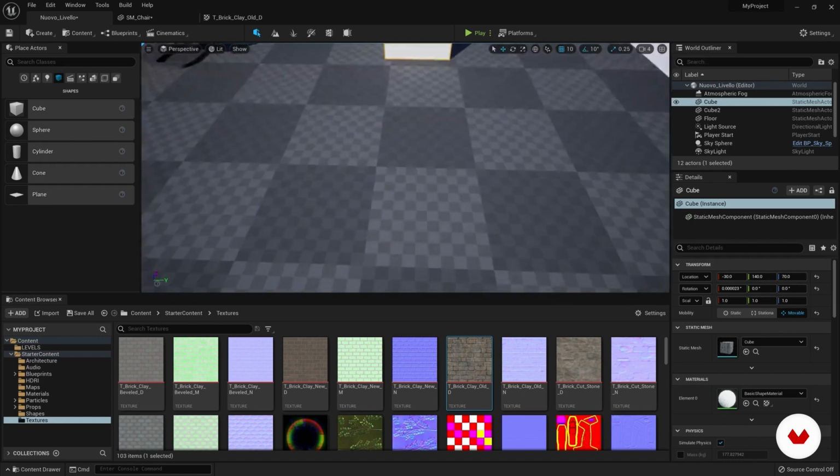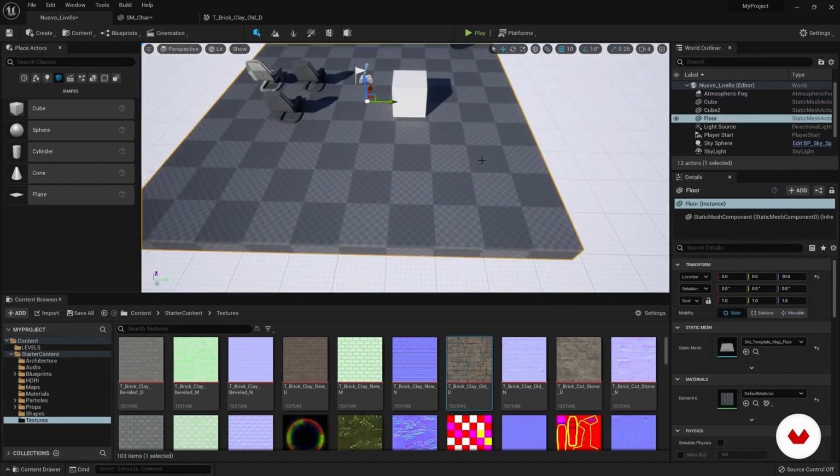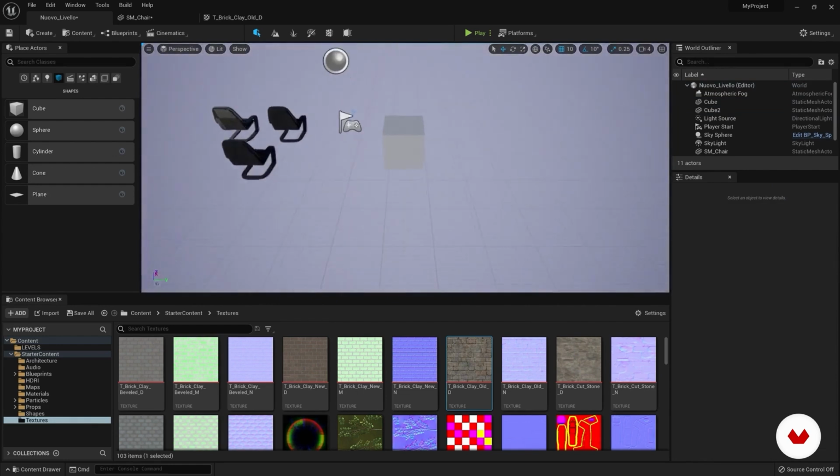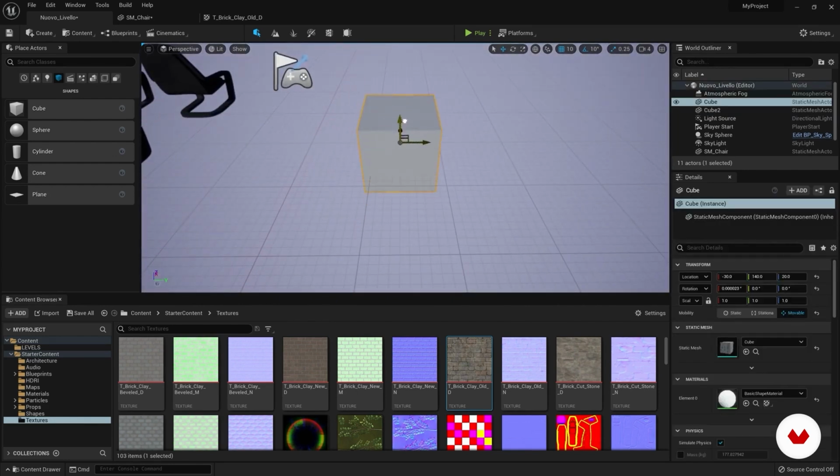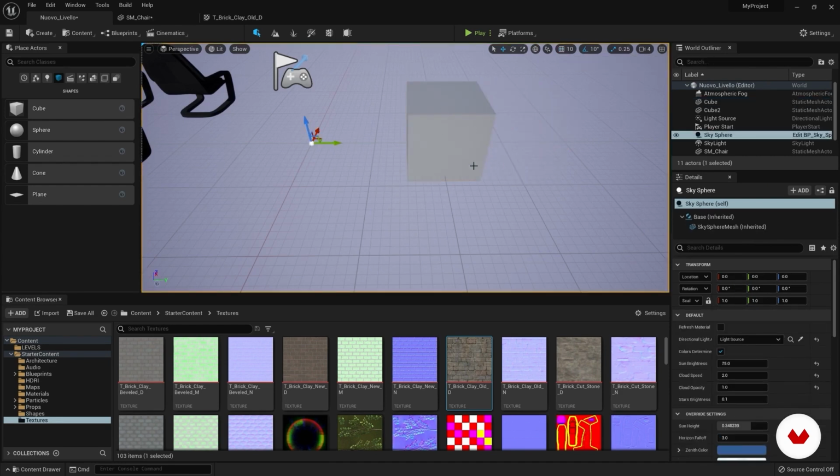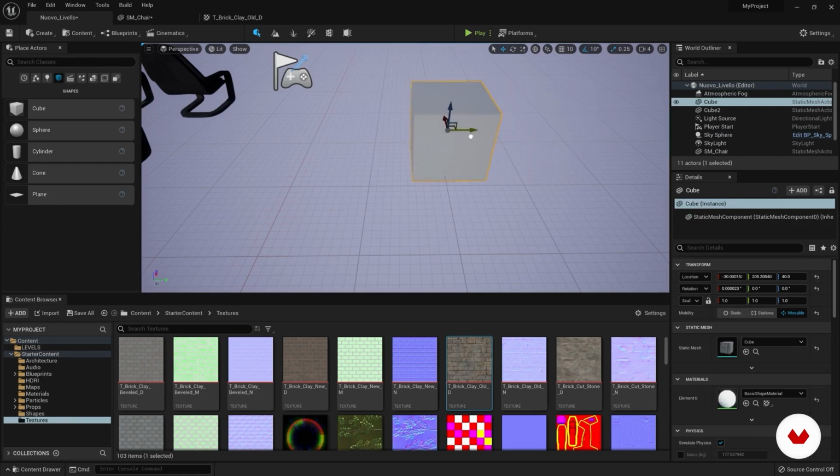Snap to the grid. Let's disable that plane. Let's go see that there is a grid. And the object will move according to the grid. We can create a snap size based on the size of the grid. That we do 10 and 10. And it means that it will move to one of these, which is 1/10 of a grid cell. We are going to disable it. And we see that we can move the cube and it won't snap to the grid.